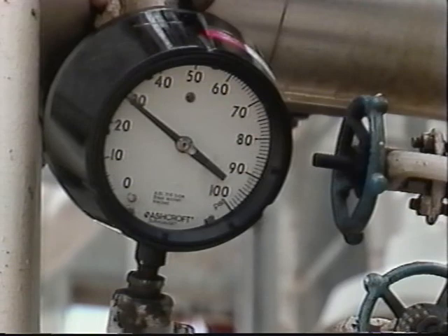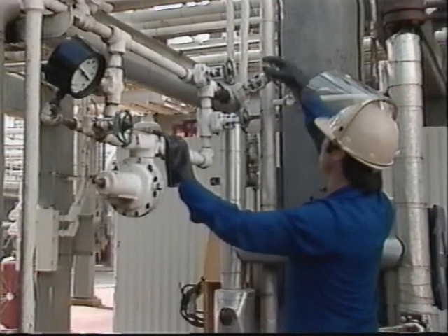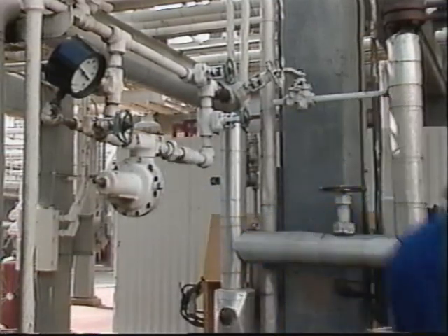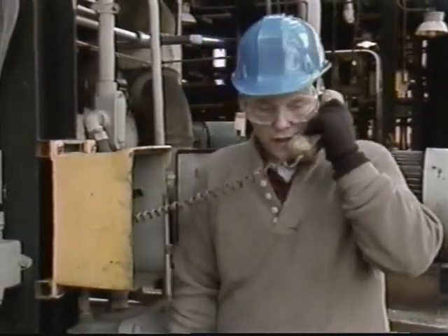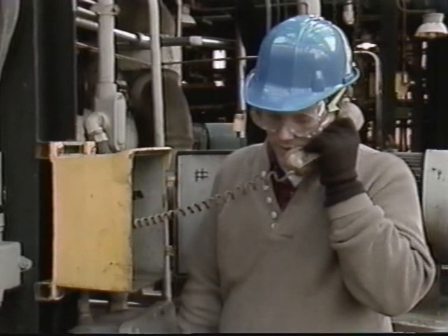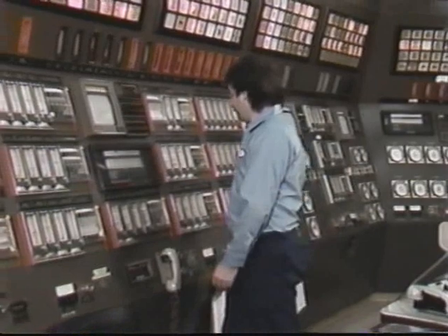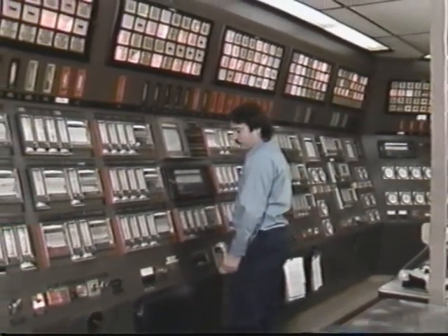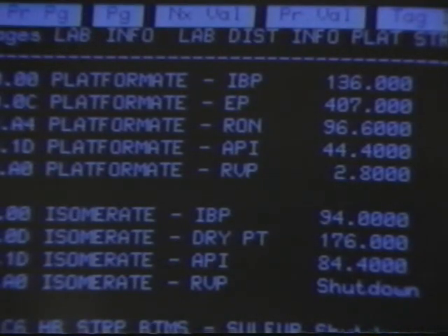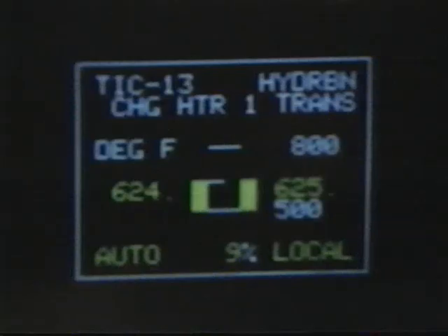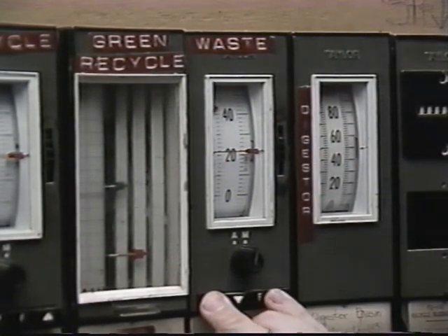Process disturbances can have serious downstream consequences, so you may have to consider the possible effects of the problem before you start exploring its cause. For example, you may need to notify personnel in other process units that there's a problem in your area that could affect their operation as well. It may be necessary to make temporary adjustments to operating conditions to help prevent the process from getting dangerously out of control. This could involve actions such as reducing production rates, lowering temperatures, or changing flow rates within the process.